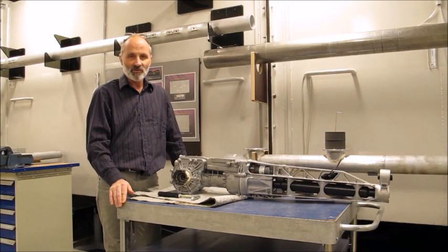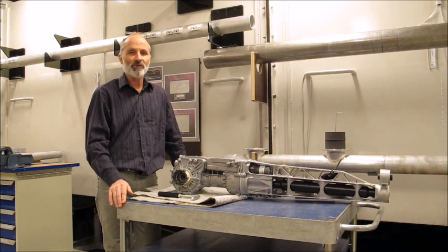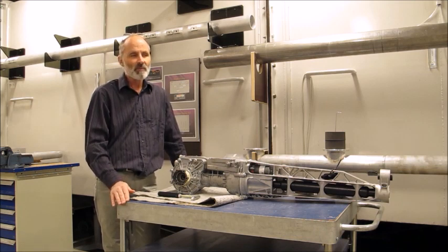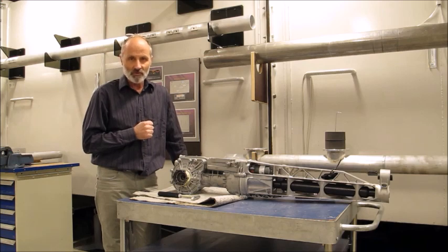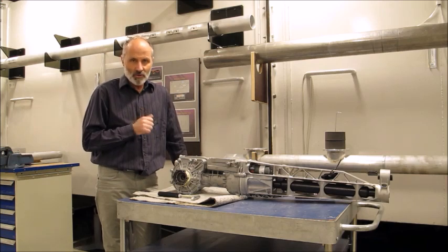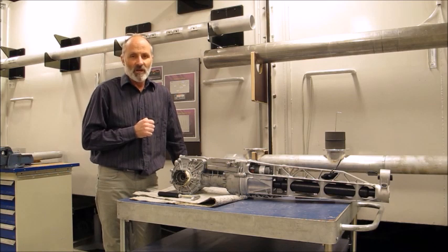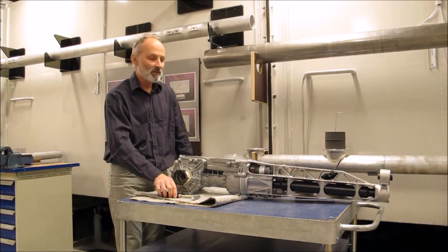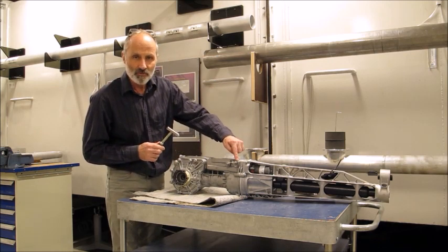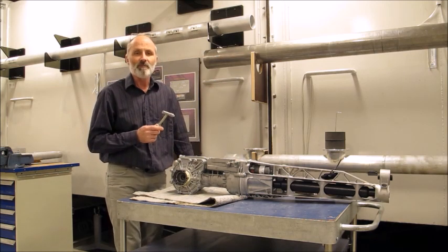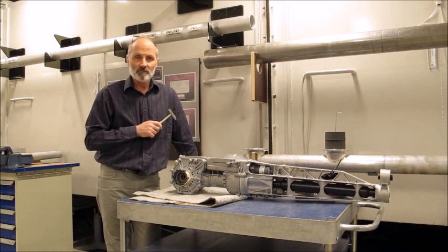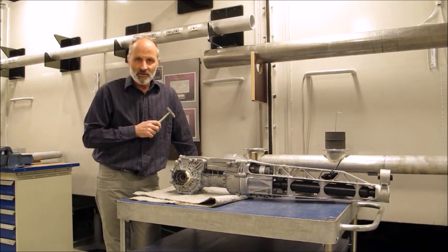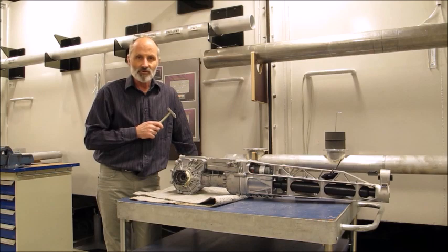In experimental modal analysis, we do not normally need to measure the full frequency response function matrix. In the ideal situation, in fact, it's only necessary to know one column or one row of the frequency response function matrix. So that poses another question. Should I measure a column by moving the response transducers, or shall I measure a row by moving the excitation force? This presentation will focus on this kind of issues.